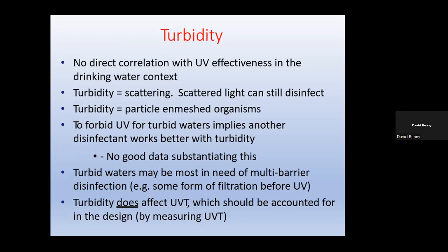So at the newly constructed San Fernando wastewater treatment facility in South Trinidad, we have microfiltration before the UV radiation. So the effectiveness is much more than we would have had at the Beetham wastewater treatment plant.